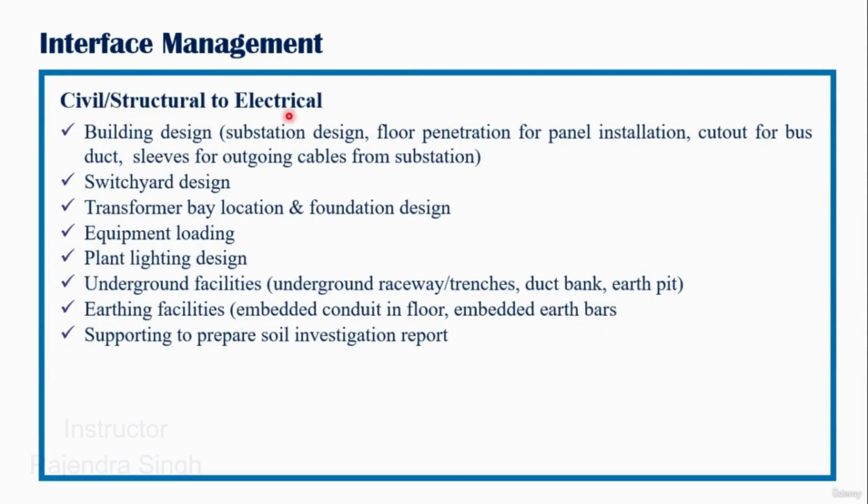For civil and structural team to electrical: the building design, substation design, floor penetration for panel installation, cutout for bus ducts, sleeves for outgoing cables from substations. So all these details, RCC, earthing, etc., are part of building design, and we have to give clear-cut instruction to civil for the substation, the floor cutouts, the cutouts for bus duct, supports. All this structural input should go between civil and structural and electrical.